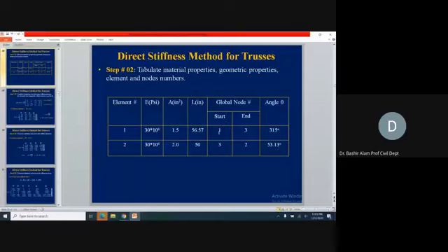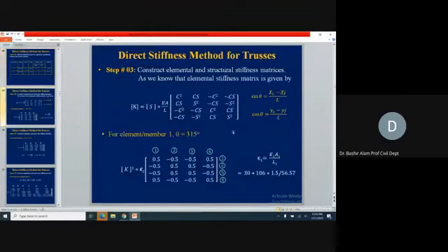What will be the address of this when we generate the stiffness coefficient matrix? So here now, this is the basic equation. And the angle we are using with this element number 1. 1 was the starting point. There the displacements were 1 and 2. And at the other end, joint 3, the displacements were 5 and 6. You see here, these are becoming the addresses of this coefficient matrix now. The angle we are putting is 315 now, so you can verify this 0.5.